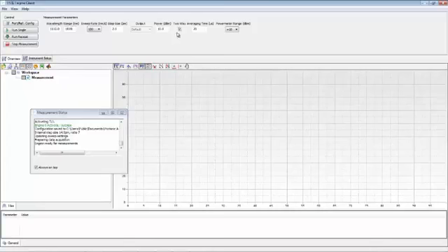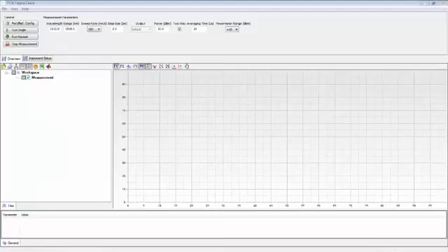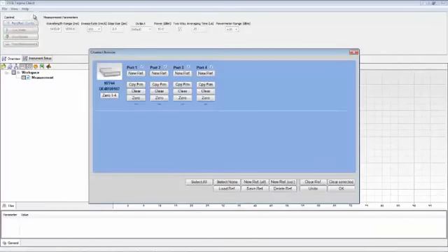Another unique characteristic of the 81960A is that we can perform a two-way measurement. So it's a bidirectional sweep where it grabs data as the wavelength increases and also as the wavelength decreases, and I'll keep the default power range of plus 10 dBm. After the measurement parameters have been defined, we can zero the power meters and also perform a reference sweep by selecting the port reference configuration button shown here.